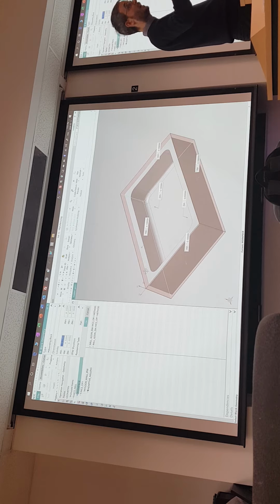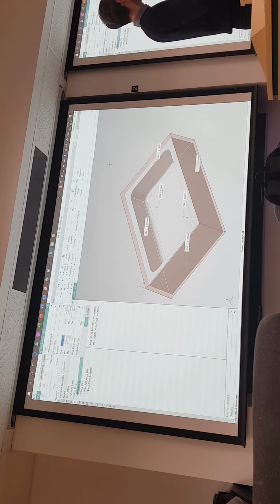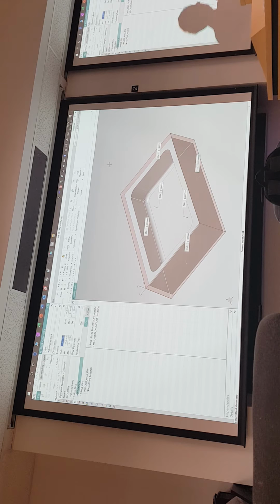What's important is that on the machine, obviously your block is not square, so you have to line up your long edge with the X-axis. Otherwise, if you do it the other way around, you're going to get a weird result. You're not going to make a part out of the block. Your block will be like this. So it's important to take your machine coordinate and put it correctly in your CAM software, and then double check that when you set up your workpiece, it matches what you defined.